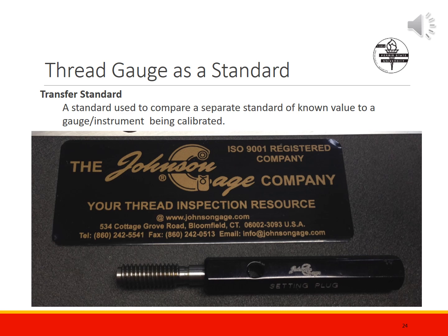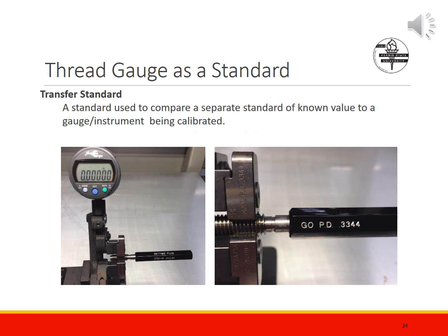This is a stepped thread gauge, and it might be kind of hard to see with the YouTube video resolution that you're watching this on, but as we've now learned, the thread plug gauge checks MMC inclusive of the major diameter of a nut or threaded hole. Having a stepped threaded gauge allows the user to independently check for pitch diameter and then pitch diameter plus major diameter. In this case, this gauge is used to set up a variables measurement gauge for measuring OD thread.